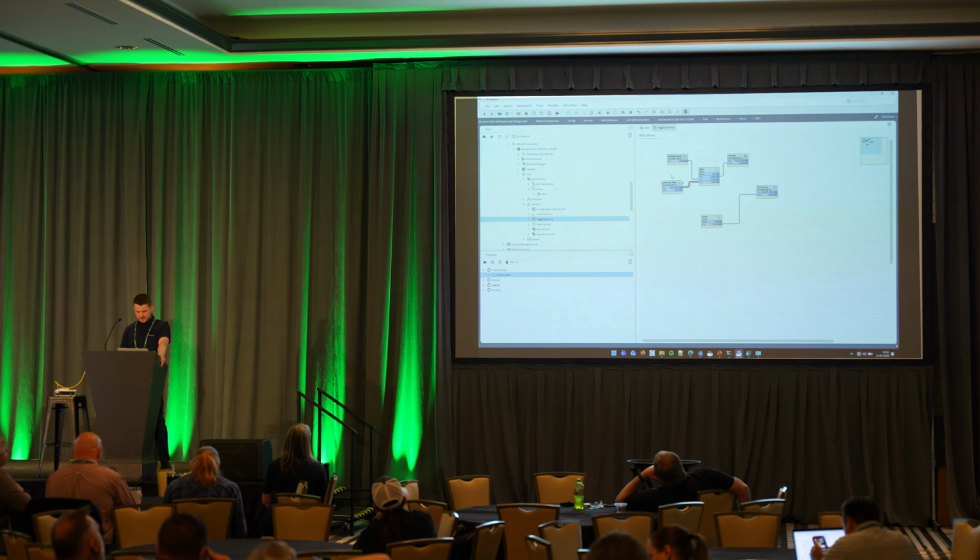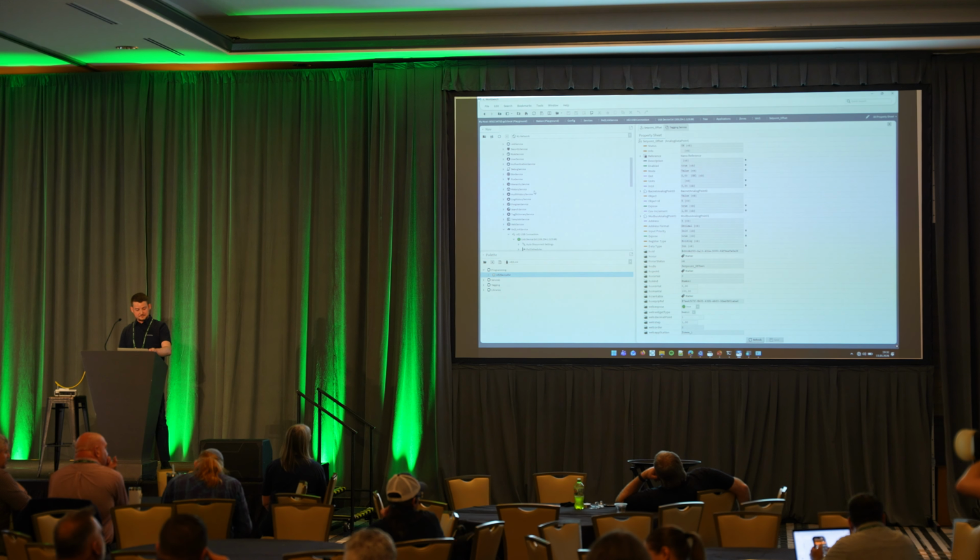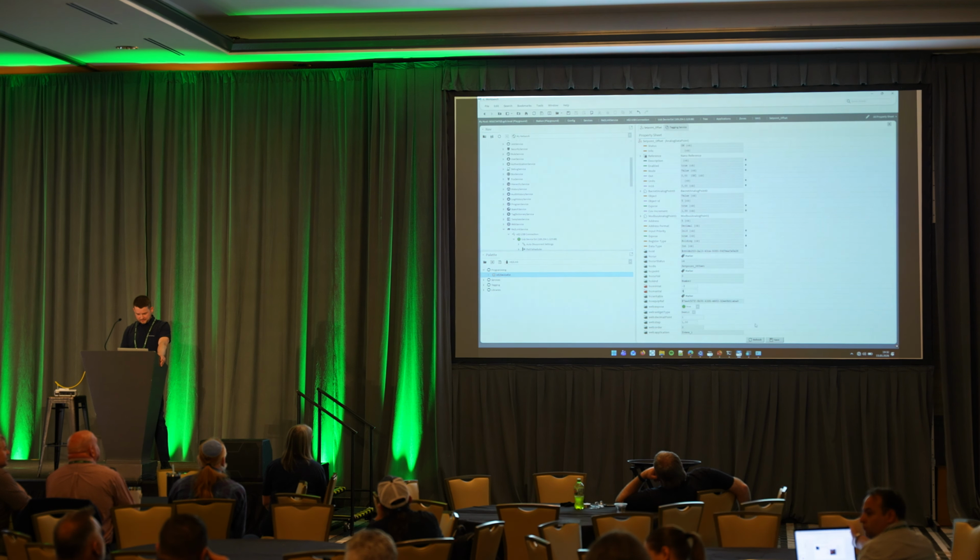So for that, we go back here and open our offset point. And what you can see here, these are just the standard haystack tags we just apply to the device on the fly. And it comes from your haystack service inside Niagara. So what we can do now is just apply minimum value and maximum value, which is also a haystack tag. So from -3 to 3.